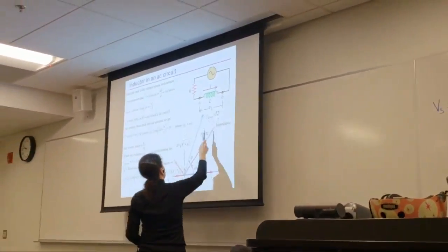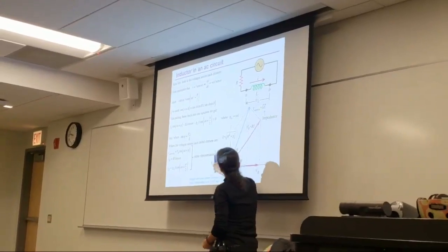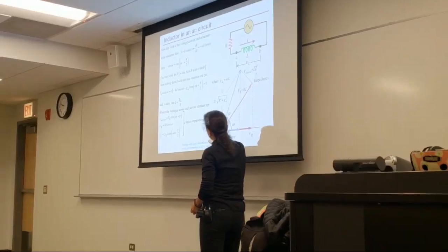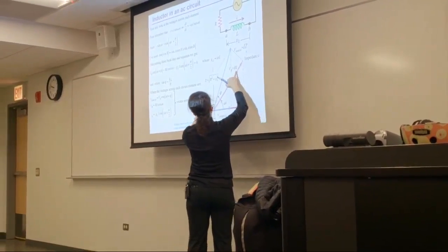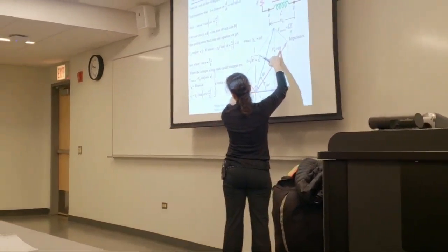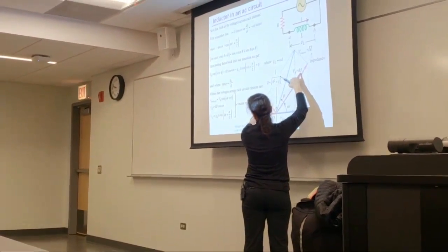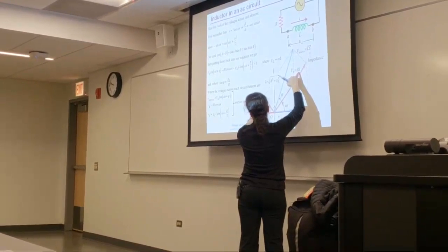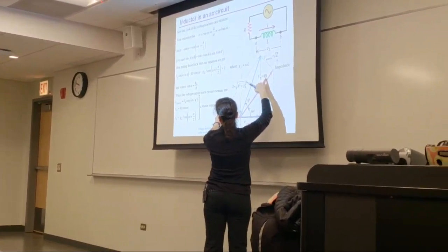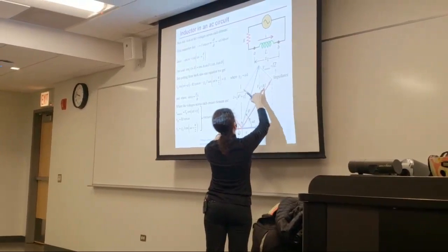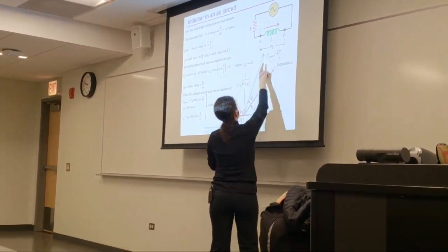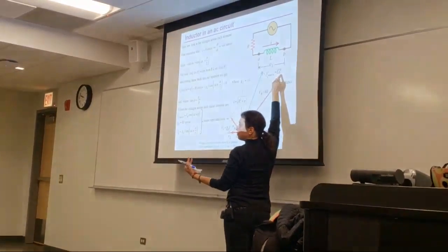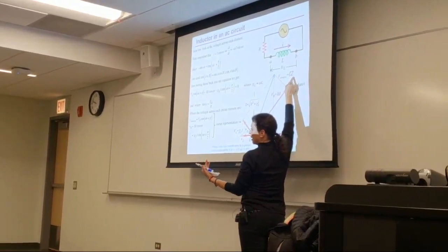Right? Now, because the voltage across the inductor and the voltage across the resistor are proportional to the maximum current I, as long as I define the reactance of the inductor as omega L in ohms, and R is in ohms, then I can also define the voltage source as having a current times another variable that depends on resistance, and that we call the impedance.